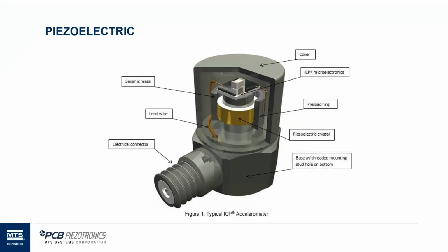And that connector is wired to the circuitry inside, but we'll get back to the center of it. In the center of this, we have the mechanical ground, and you see that as the gray post extending up through the middle of the device. And then immediately after, the bronze color element in there, that's the actual crystal. Okay, in this case, it's an annular shear crystal.